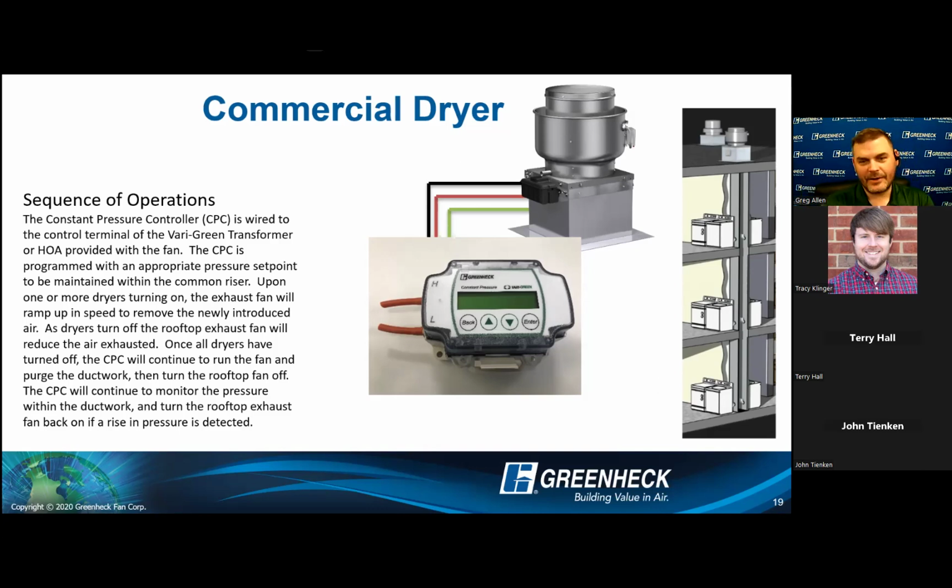I look at this and say, I could do this just as well with a building automation system. I could take a BAS and a differential pressure transducer. Those two can talk. I can have someone program that BAS to maintain a set point, and I can use another output from the BAS to go to an EC motor or to a VFD and send a 0 to 10 to it. I can do all these applications on that higher end. But in this scenario, I just had no need for all that ability and expense. I'm going to do it with a little standalone control.